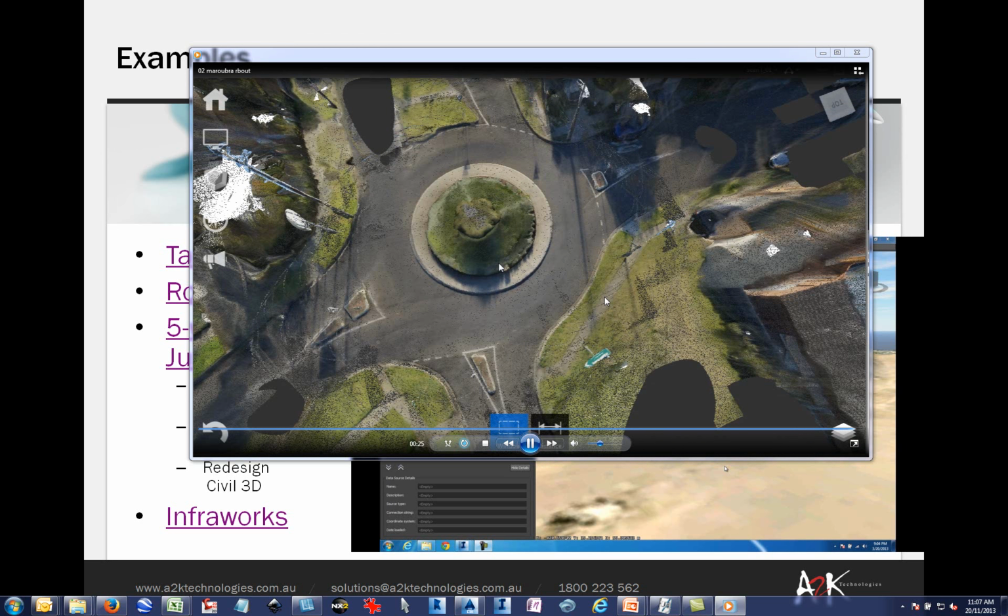So what you do with this software is you've got a selection option. So I'll pick fence. Now I'll do this in two different ways. One is where I draw a very rough circle here. I'll highlight a bunch of points, and I've got the option to delete these points. So that's one way of doing it. It's not the best way because you don't have much control over the points afterwards.